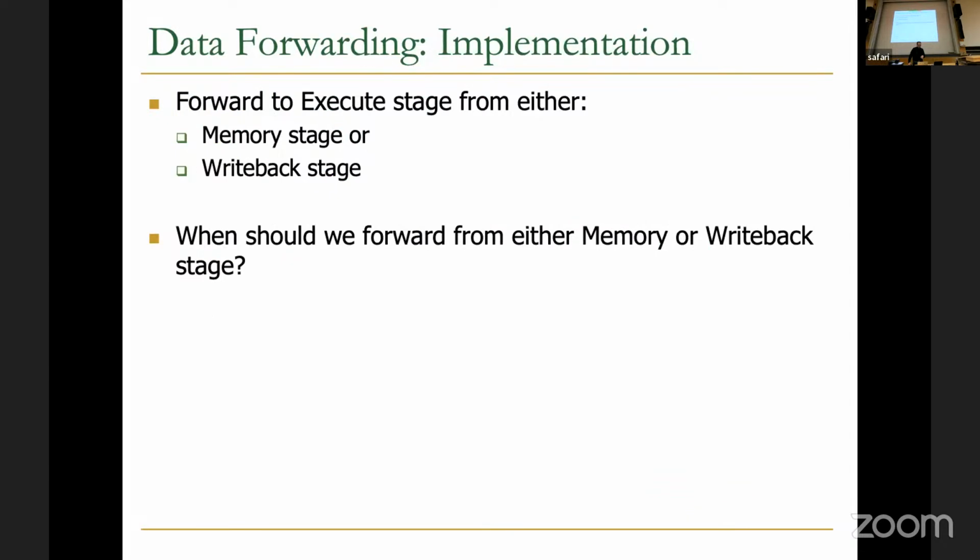So in data forwarding, we forward to the execute stage from either the memory stage, which is the latched output of the ALU, or from the write back stage, the beginning of the write back stage. Then we have this question: when should we forward from either the memory or write back stage?